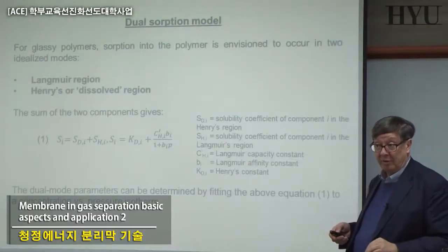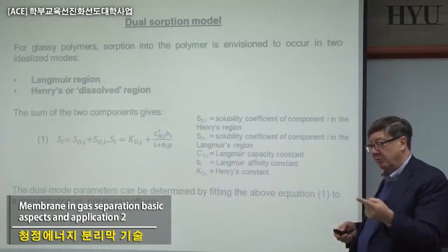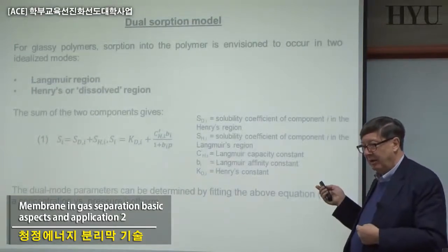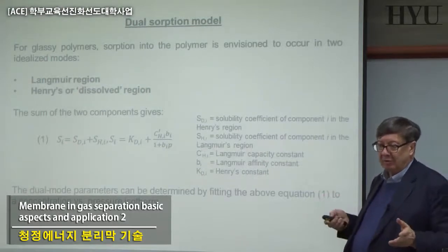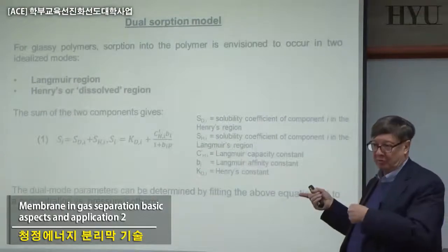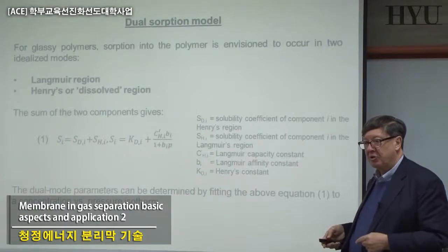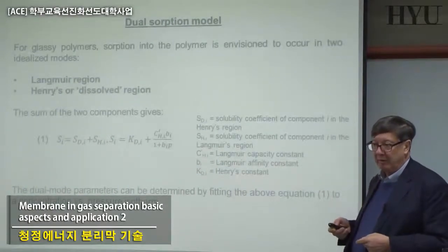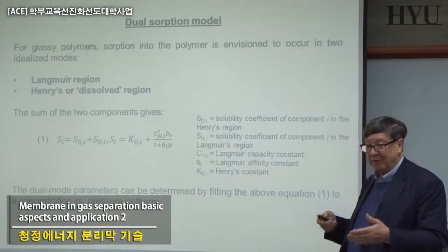Not so easy. There are a lot of situations, for most of the membranes you are preparing, particularly glassy membranes but also some rubbery membranes, in which Fick's law is not valid. You have a lot of anomalous diffusion related to phenomena that take place for the species that penetrate your membranes, and so you have to simulate it to understand these different phenomena.